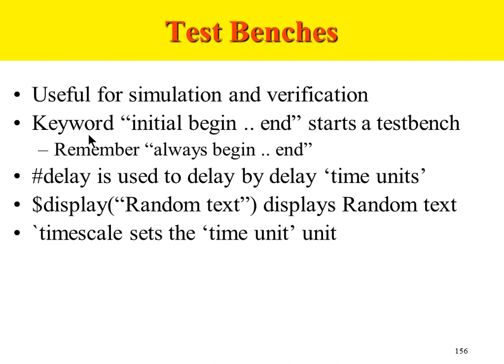For design purposes, we have seen that only a certain part of Verilog is synthesizable. That means only certain sections of Verilog can be used for designing a circuit that has to be implemented on a chip. For a test bench, nothing is going to be implemented on the chip. So the entire Verilog language is available to you to be used in the test bench. Whatever is part of the Verilog language can be used in test benches.